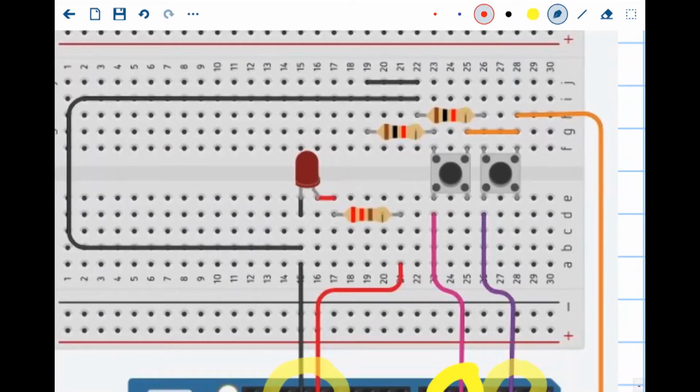The default path in this, so if you are playing with Tinkercad afterwards, you will have this switch in the CAD, and by default, this pathway is open. And when you press the switch, this pathway opens up. So that means, to make it clear again, if you press it, this is connected. If you release the button, this is connected. So when it is released, there are 4 pins in the switch. When the button is released, the vertical ones are connected. When it is pressed, it is connected in this way.